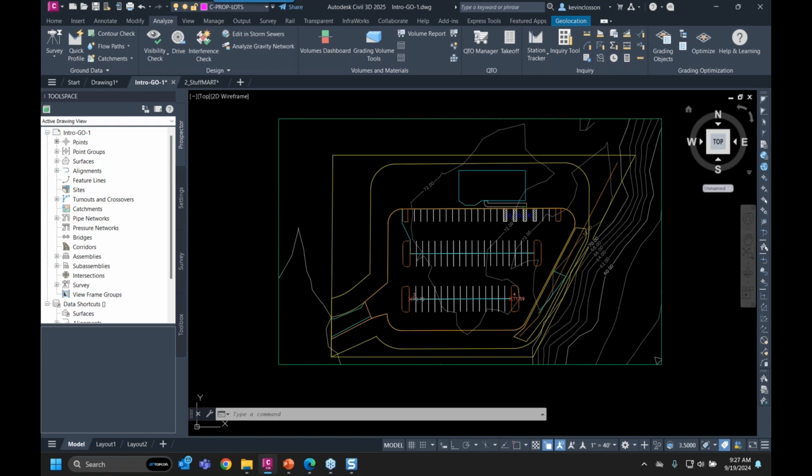You'll see that some of the lines give you the ability, when you go into the properties of it, to say, okay, this line is important, but it's not nearly as important as, say, a drain line. If we have something that's supposed to be a -1.5% going in a key direction, we want that surface to treat that like a break line. That's a true constraint. But you could have some other lines that might have a little bit of fudge factor in there.